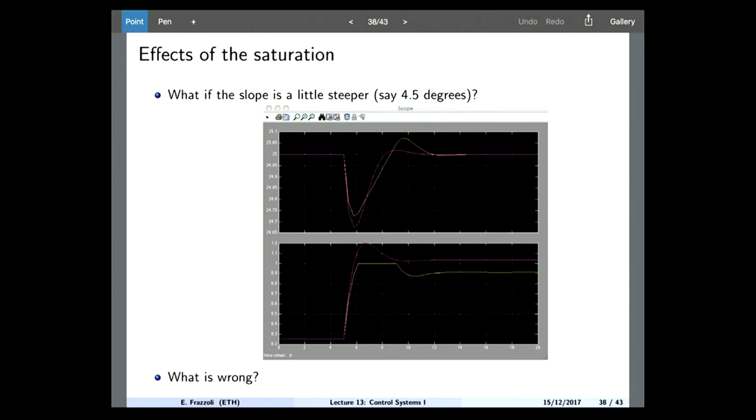Okay, so in reality, for example, what is the difference, right? In your linear approximation, there is no bound on how much you can choose U, right? How large you can choose U, right? You can choose your control input to be as large as you want. In reality, sorry, your maximum torque, your maximum power of your engine is this much, right? And I cannot increase it beyond a certain limit. Okay, so this is something that is called the saturation. Okay, so what you see the effect of the saturation here is the following.